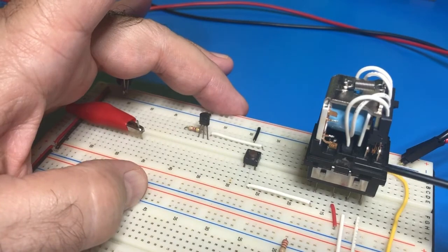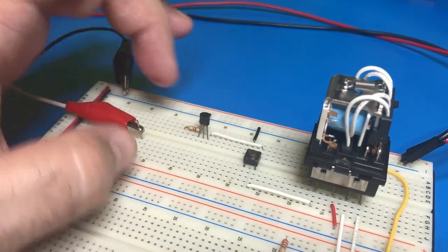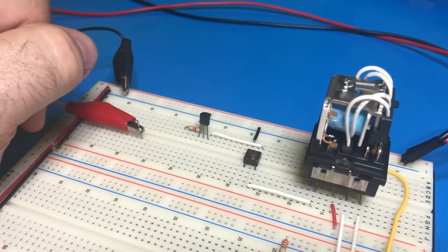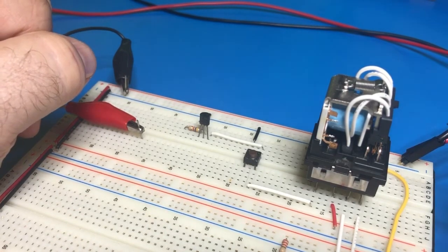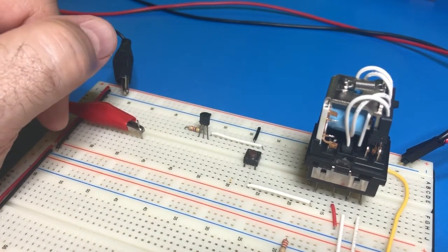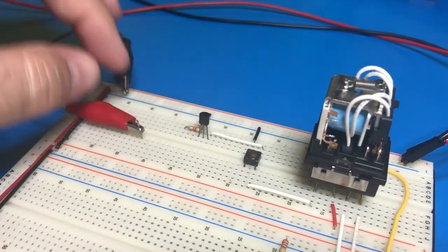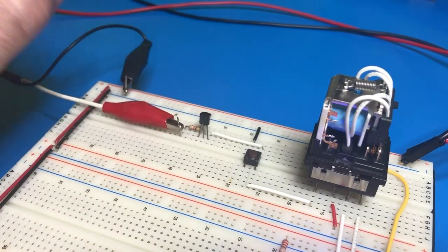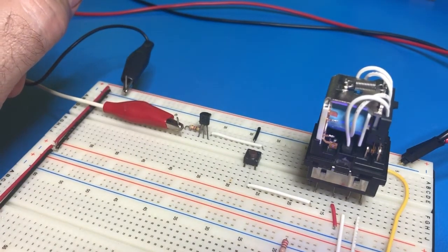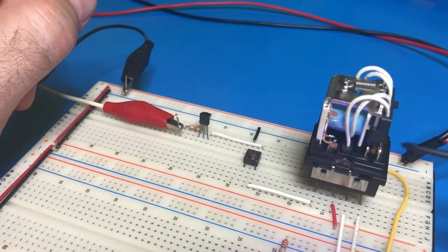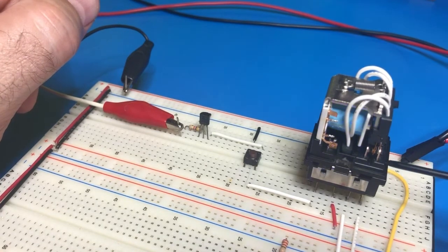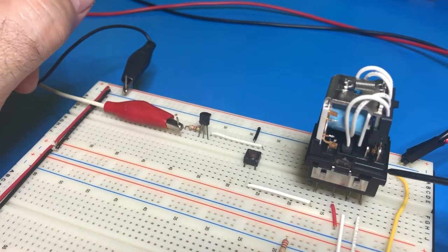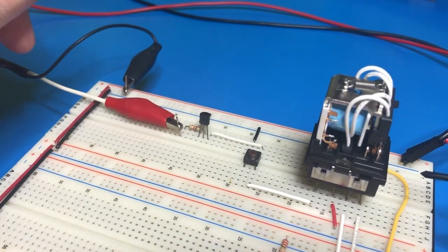Another thing that I have here is a pulse generator in my lab, and I'm going to control the relay by a pulse signal from that generator, and I'm going to do it through this transistor. So let's see what happens. So that's just 1 cycle per second. You see how the contacts move? And we say, this relay is just a switch that we can control.